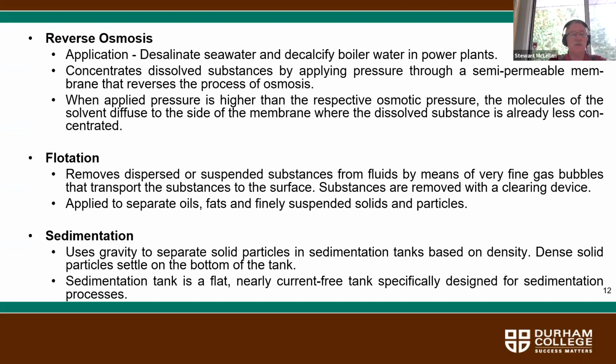Flotation removes the dispersed or suspended substances from fluids by means of very fine gas bubbles that transport the substance to the surface. Substances are removed with a clearing device, applies to separated oils, fat, and finally suspended solids and particles. Sedimentation uses gravity to separate solid particles in sedimentation tanks based on density. Dense solid particles settle on the bottom of the tank. The sedimentation tank is a flat, nearly current-free tank, specifically designed for sedimentation processes.